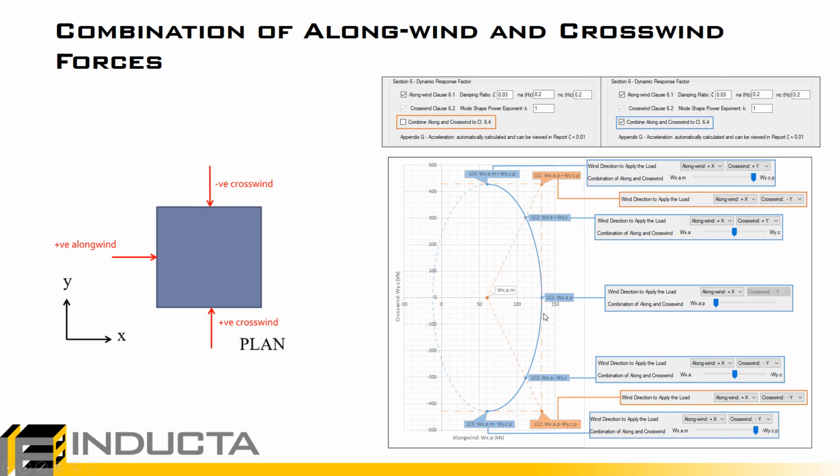We would then repeat it for the negative values, and we would then have to repeat this whole table another 3 times. So where we had 5 primary wind cases plus an additional 15, we have 20. So we see that by being accurate, by being less conservative, we have to have many more primary cases and many more wind combinations. But if we were just to use these peak values, being more conservative with the peak values, we would only have to have 8.